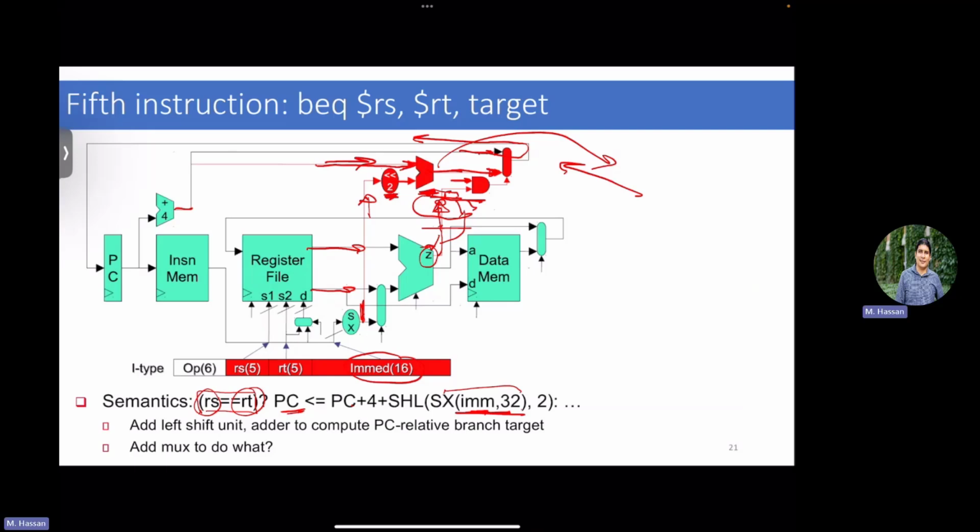Well, ignore the mux for now, assuming that we only have a jump. So I continue with this, but I need to simply add the last 4 bits of your program counter. This is your dashed line here. It assumes that you take the last 4 bits of your program counter, augment it to your 28 bits of your immediate value jump after shifting by 2, and then you load it to your program counter.